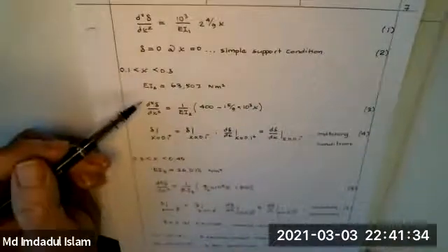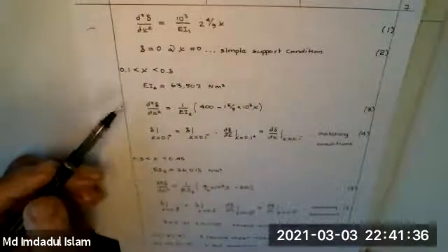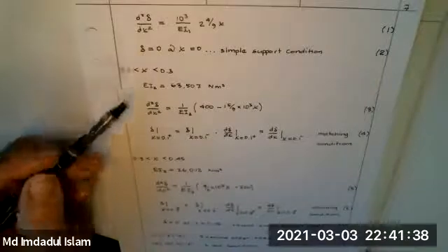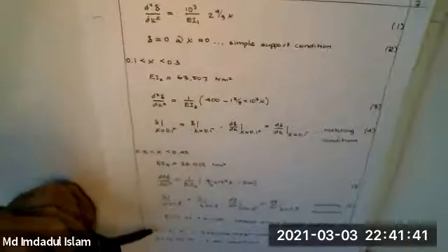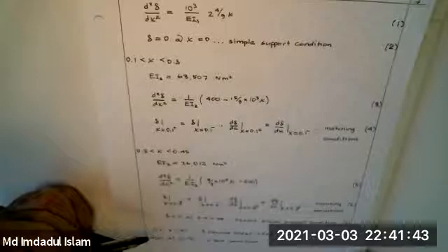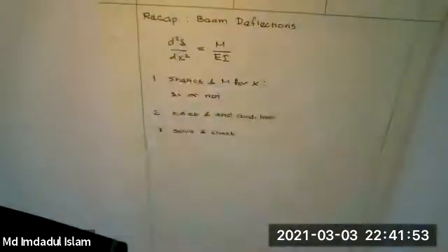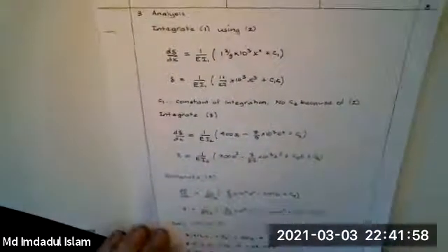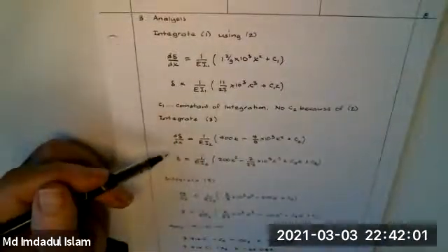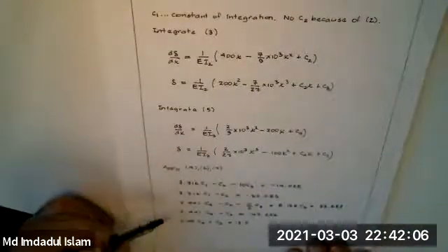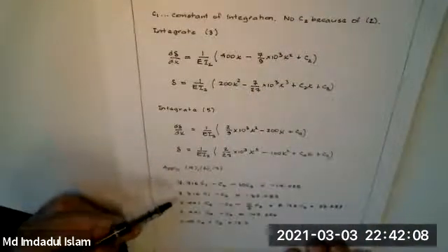So in these 3 differential equations, 1, 3, and 5, we have 3 second-order differential equations. The problem is statically determinate, so we need 6 end conditions. We have 1, 2, 3, 4, 5, 6. So it's a well-posed problem. The analysis is really straightforward. You just integrate and apply the conditions. I've worked this to 3 decimal places.